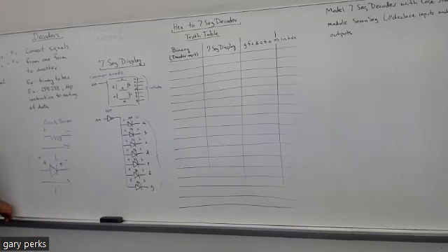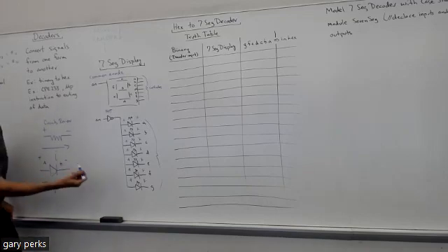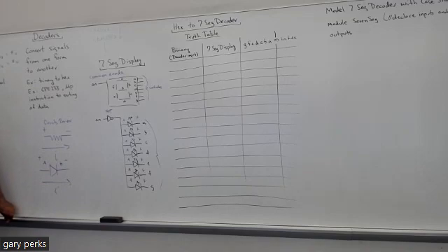The way diodes are constructed, if you try to get current to flow cathode to anode, ideally it won't happen. Ideally, you get zero current. Now, in reality, you get a smaller current. But to get appreciable current, you've got to have the diode biased like this. It's called forward bias. I'm sure you've heard that term.